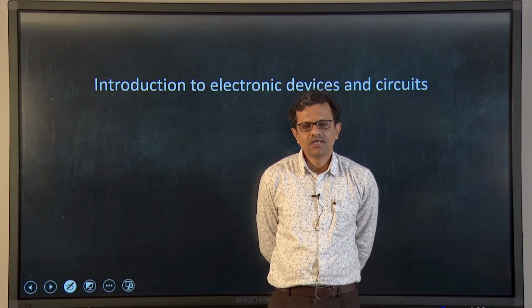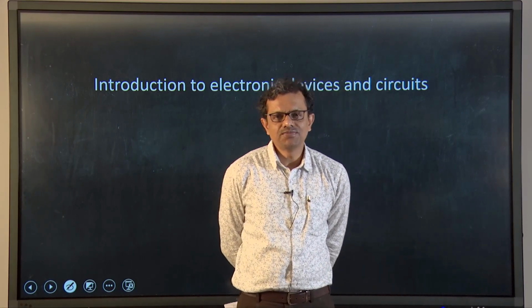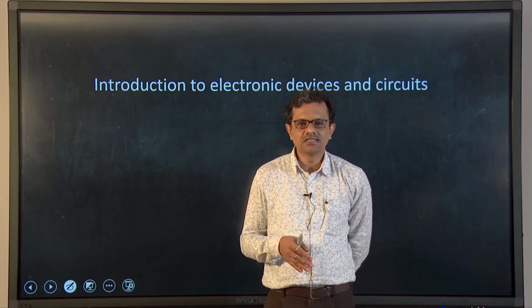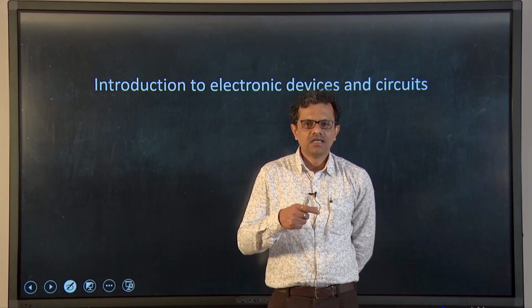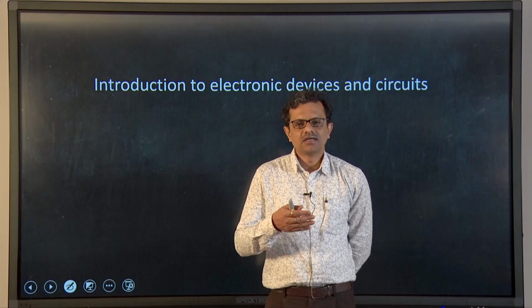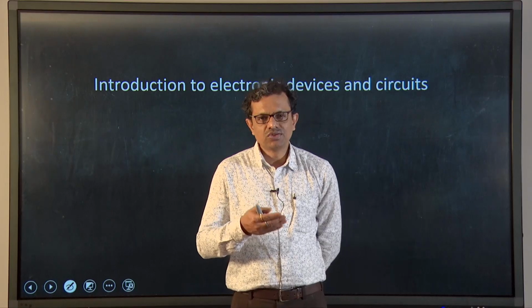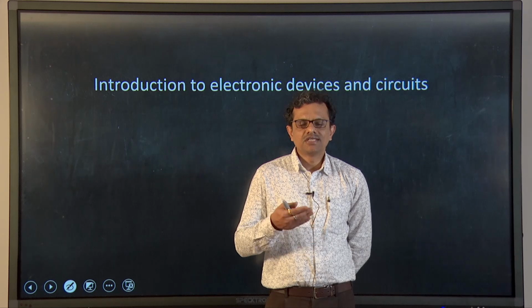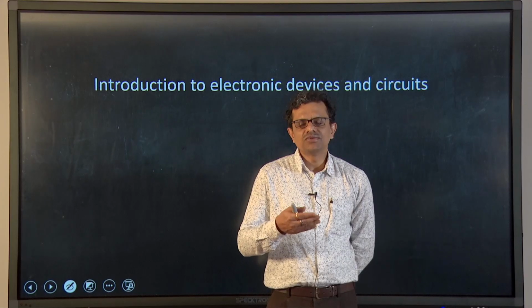After receiving inputs, the ECU has the provision to compare them, and if they do not match the stored data in the ECU, it will provide feedback to the actuators to adjust the engine operation, such as fuel injection, mass of air introduced into the engine cylinder, temperature of the engine block, temperature of the incoming air, and temperature of the exhaust gas, so as to restore them to the design data.